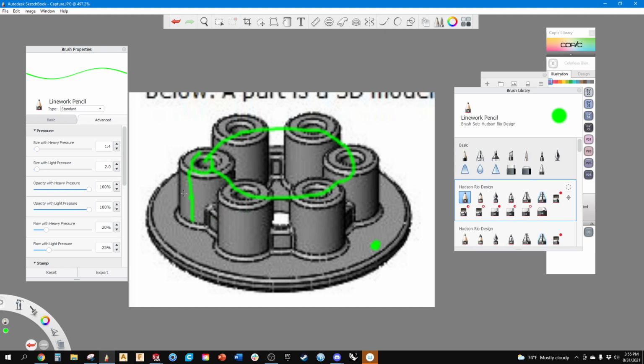What I could also do is draw one circle, extrude it, and then use what's known as the pattern command, and do a circular pattern. Every way is right. There is no wrong way. Each way gives you a little bit of different freedom.